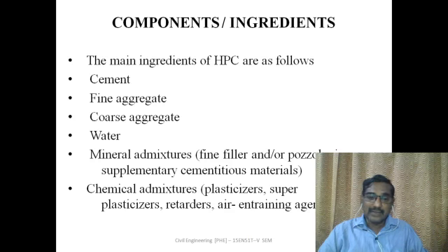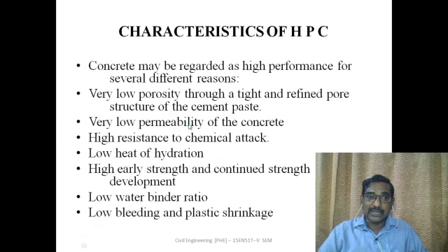The mineral admixtures are pozzolanic supplementary cementitious material, used as filler material, and the chemical admixtures are plasticizers, super plasticizers, retarders, air entraining agents, etc. as per their requirements.